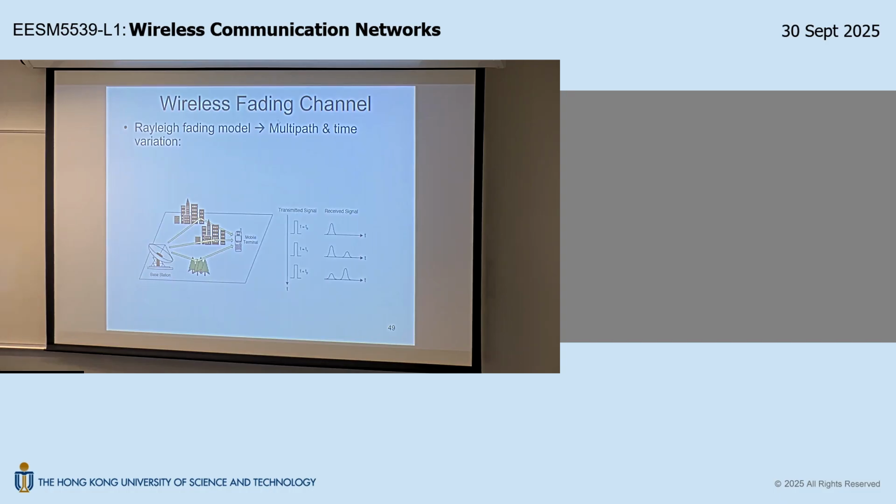So this is due to distance separation, right? We can do some back-of-the-envelope calculation. Now, if you double the distance from the base station, your receive power, let's say it's inverse square, alpha is 2. If you double the distance separation, your receive power will be reduced by 4 times, right? So 2 times means 3 dB, so 4 times means 6 dB. That means you will see a 6 dB difference when you double the distance.